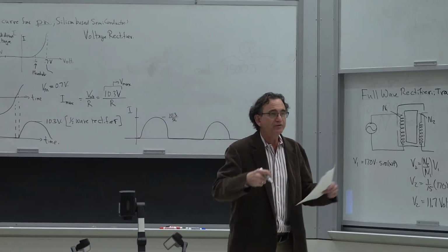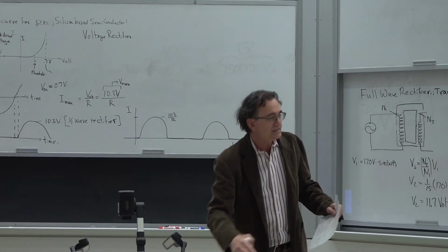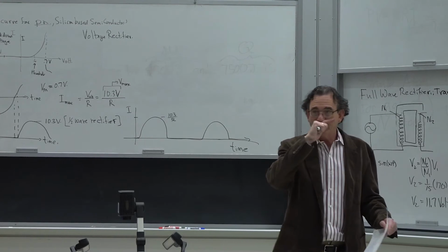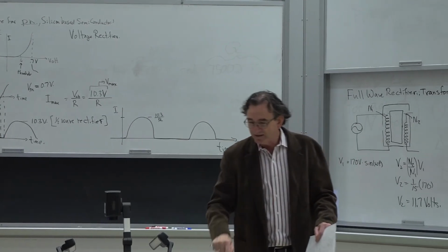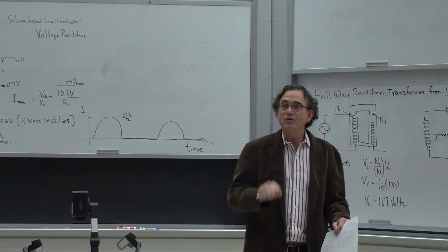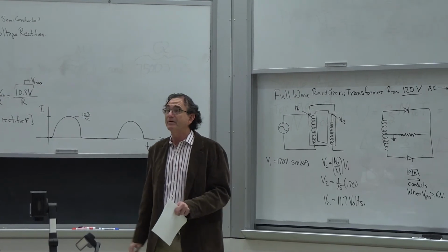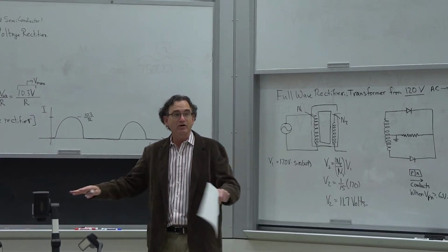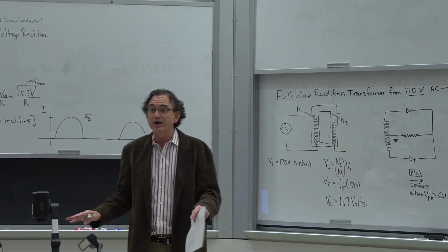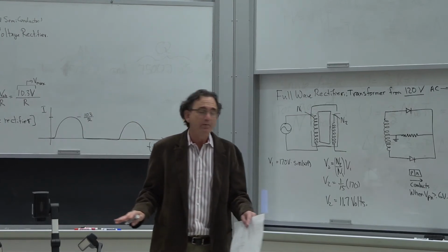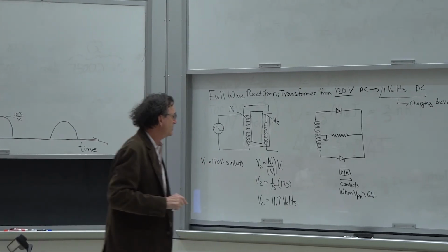And ground is that infinite reservoir of conducting electrons that's connected to the metal and the table and the floor. If I have a large copper piece of stranded wire and I nail it to the metal in the floor, that's my infinite ground, right? By infinite I mean an infinite reservoir. I can pull as much charge off it as I want, and it's not going to change the charge of the ground significantly. Okay, so that's just a backdrop on grounds, in case you wanted to know a little bit more about that.